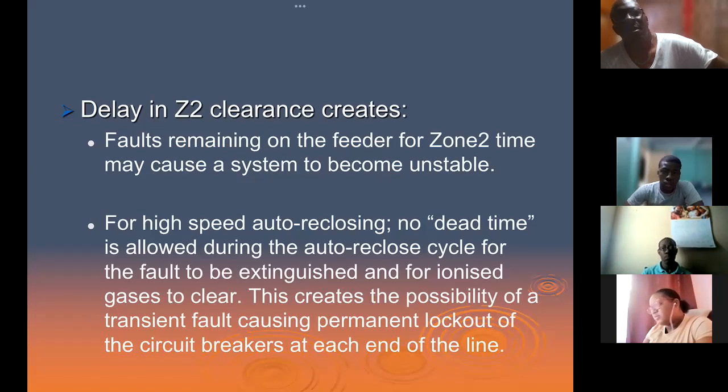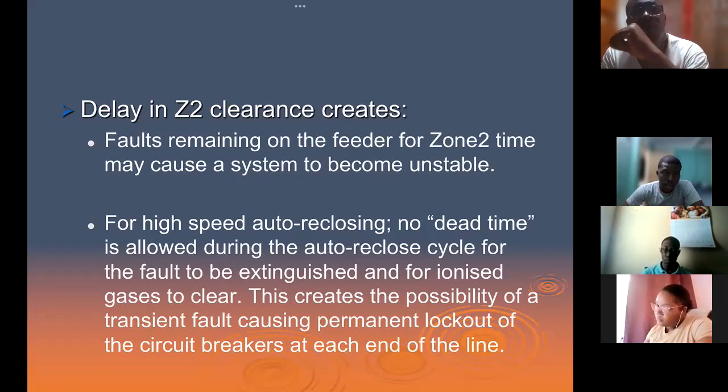Okay. All right. Now that exercise, very important lab, because what it is saying to you is that when you switch out a line, you have to switch it out from both ends. You can't disconnect one end and say, yes, the line has been switched out. It has to be removed from both ends. So if you have a fault on the line, you need to open the breakers at both substations at which the line is terminated. All right?